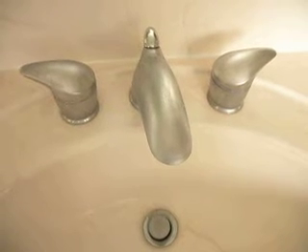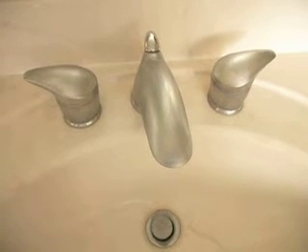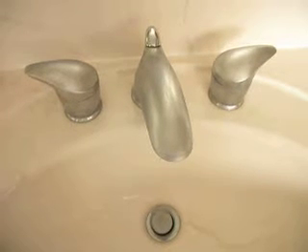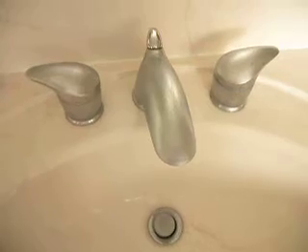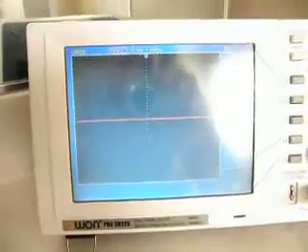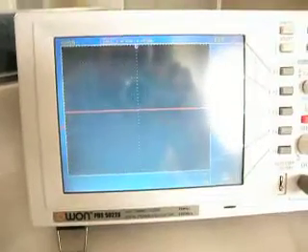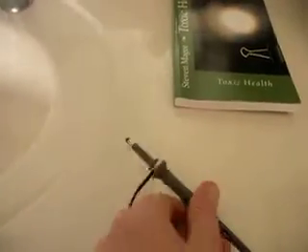I'm going to show you what the waveform looks like on plastic plumbing that is run near electrical cables and has a voltage on it through inductive coupling. To do that, we're going to use this oscilloscope, and we're going to do a frequency analysis on the waveform and see what kind of frequencies we can find in there. Right now the oscilloscope's not reading anything, and we're set on 200 millivolts per division, because we're open-ended. That's why we have no reading.